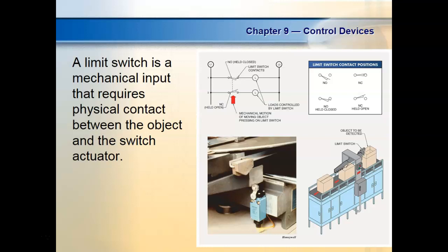And where the wire comes in through the hole, it's usually got a clamp that keeps goop out. Guys who work on it don't put the covers on right, or they don't put the clamps back on the cord coming in, and then goop gets in there, gets on the contacts, and messes them up.